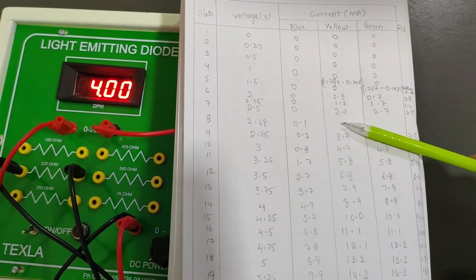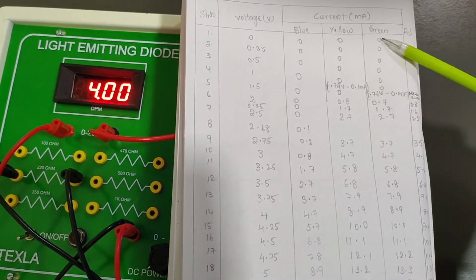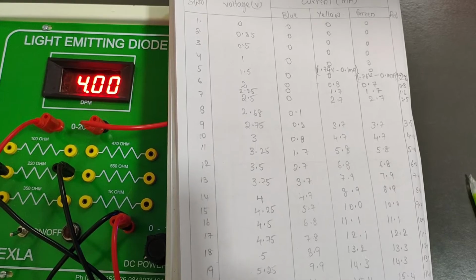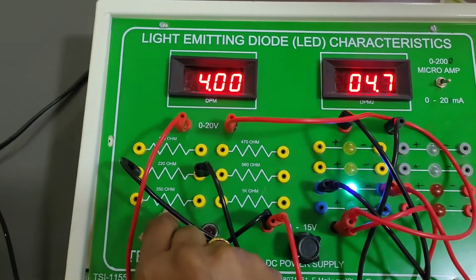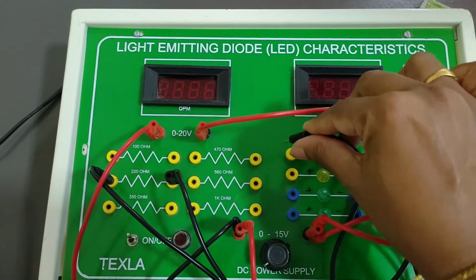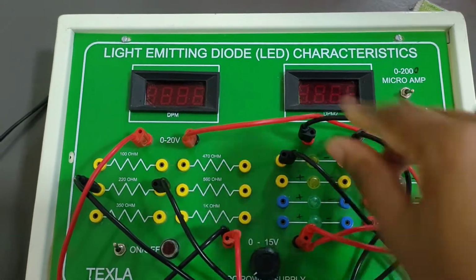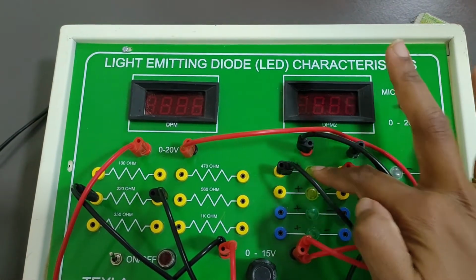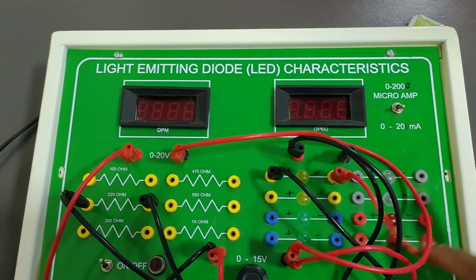Similarly, next I'll change the diode and put yellow, and repeat the same experiment. The procedure is the same, and note down the corresponding values for green as well, and for red as well I have noted down. Once we are finished with blue, just switch it off. Then simply remove these two terminals. This is the diode connection strip. I'll just change it to yellow. The negative and the rest of the connections are the same. The only difference is I have moved the diode connection from blue to yellow. Once this is done, I can go for green, this one is green, and also for red as well.